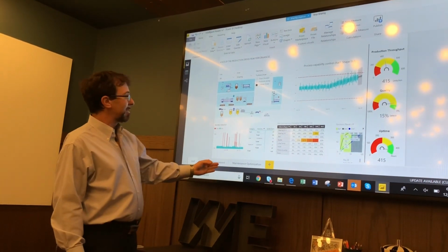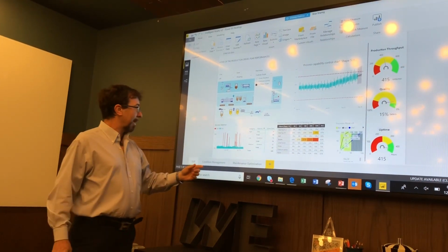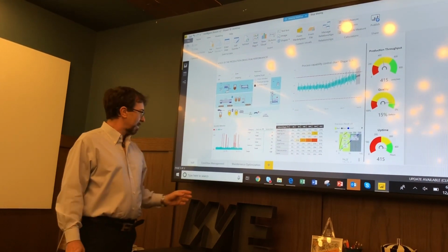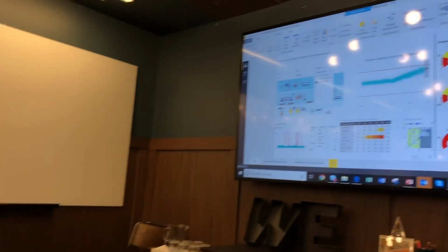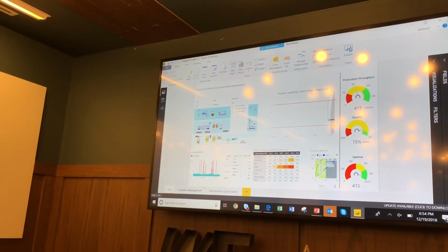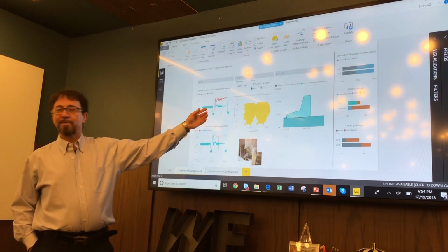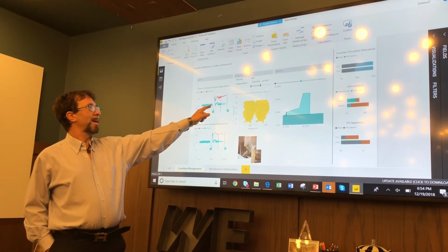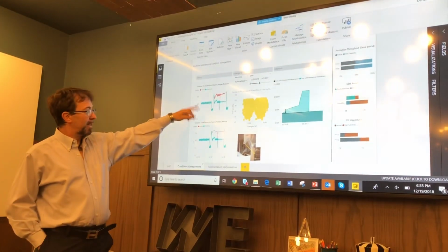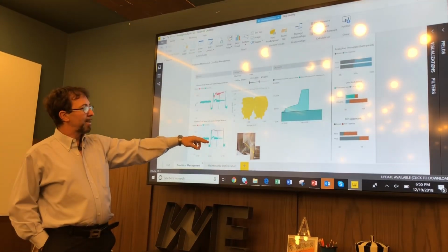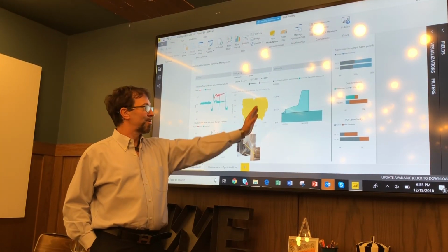Now, the next question I have is, if I'm in this situation with the blades, can I zoom in and go from the voice of the process to condition management? So if we move to condition management, you zoom into the condition of vibration, and you see that compared to the expected vibration, you have certain vibrations that are different. So that different vibration leads us to look at the harmonics of vibrations. And generally you see those two harmonics,